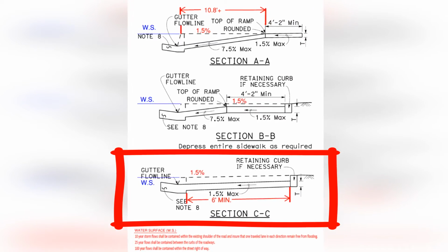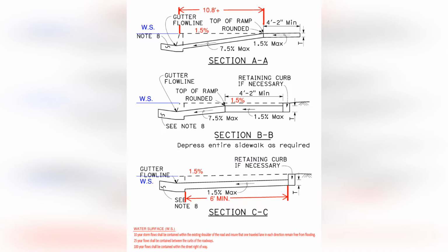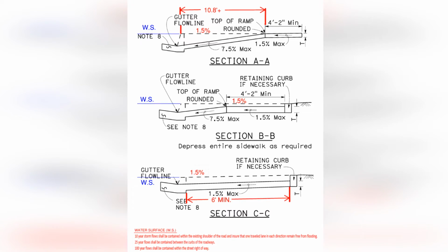I would like to point out that a Caltrans Case C, Section CC, has been revised to 6-foot wide minimal. Also, the Caltrans Case CM and Case CH ramps have also been revised to 6 feet wide minimal. The reason for increasing this width was so a wheelchair will have the correct room to turn. With this distance, the wheels should not be located and restrained on the raised truncated domes. This will allow a wheelchair approximately 3 feet for turning movements outside the truncated domes.